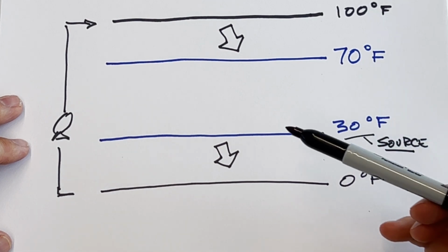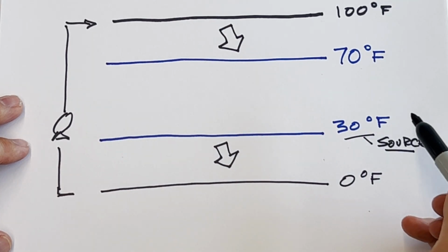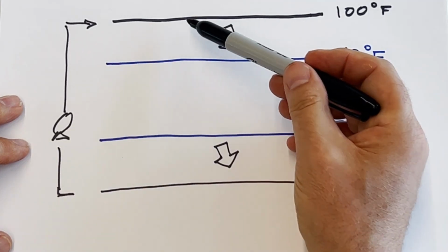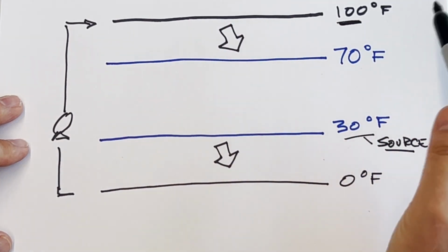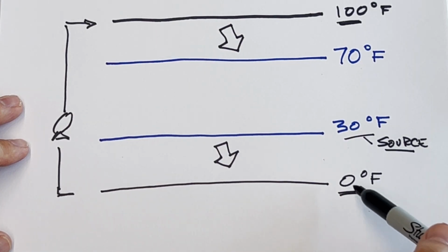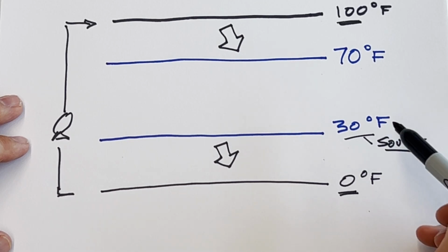A key thing to know is that the power used by the compressor, the electricity, increases with the increase in refrigerant temperature. In this case, it's increasing it by 100 degrees, and that has a relationship to the pressure that the compressor is adding to that refrigerant.